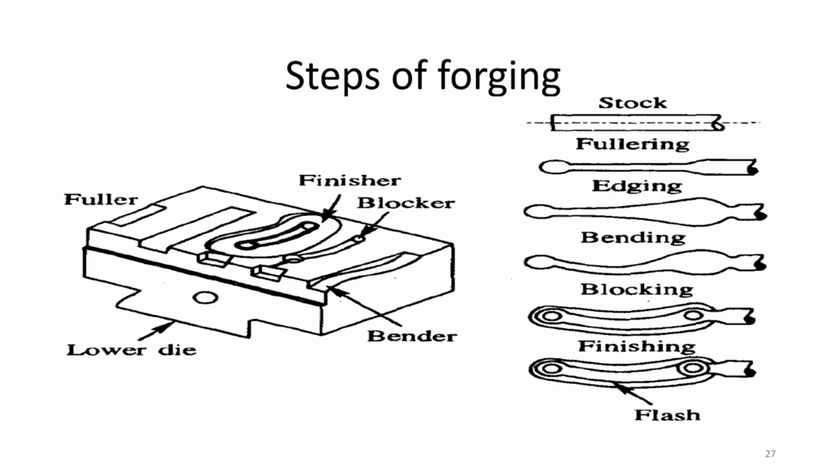Can we get the metal locked into the austenitic phase after cooling? I mean, at the lower temperature, can we lock this metal to the austenite phase? Yeah. In some steels, you have austenitic steels as well. In those, austenite stabilizers are there: nickel, manganese, and some of these alloying elements.